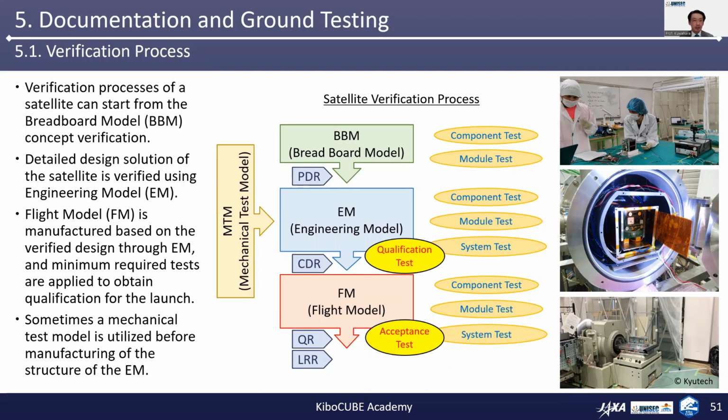Sometimes a mechanical test model, MTM, is utilized before manufacturing the structure of the engineering model, or EM. So these verification processes of a satellite are illustrated in a diagram, together with the pictures seen on the right side. The first image illustrates system integration of the satellite, while the second and third images show the thermal vacuum test and vibration tests, respectively.